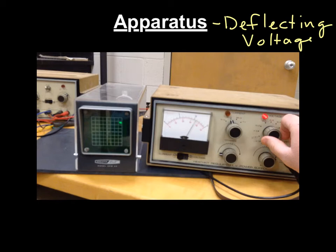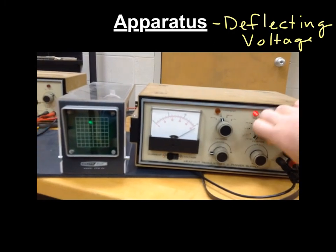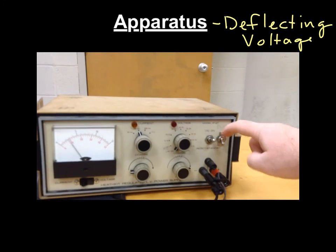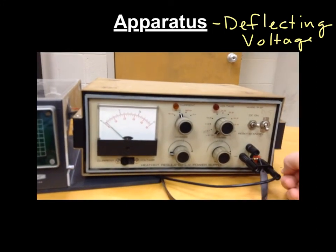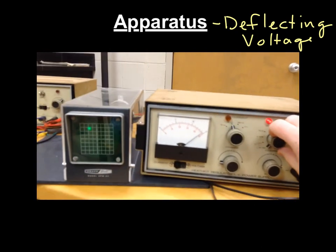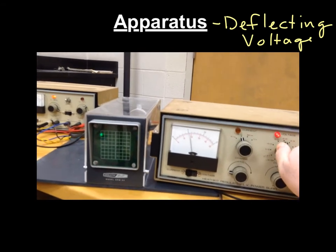So what you have to do is flip off the power, which turns this off. This is a power switch. Flip that off, safety first. Flip that probe, which flips the deflecting plates positive and negative. And now you can get your dot to go the other way.